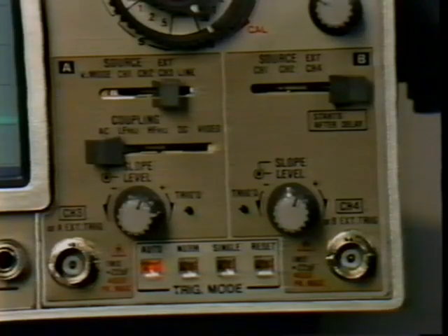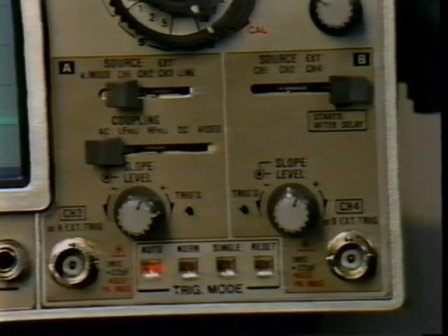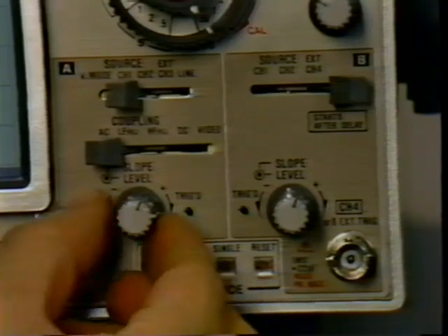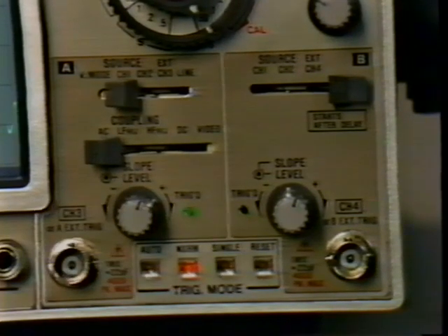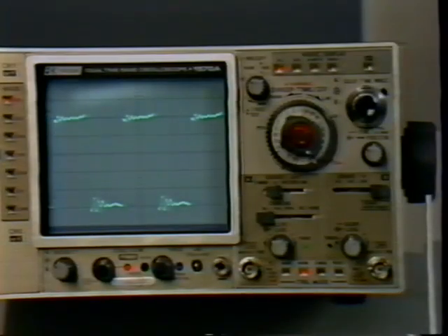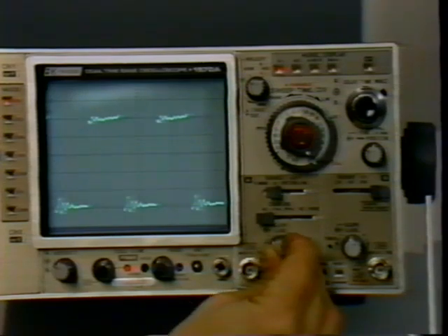In this case, we are observing only one signal, so the process is not complex. Select Internal Trigger and the channel being used, in this case channel 1. Now, select Normal Trigger and adjust the trigger level potentiometer until the display stabilizes. Now that you have a clear display, let's see what differences some triggering options can make.